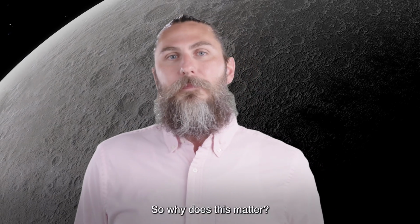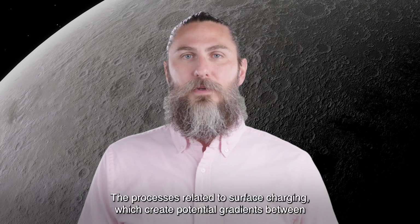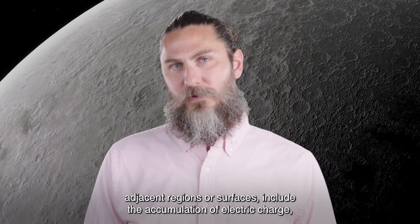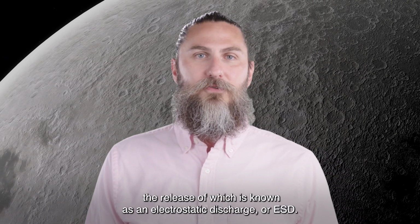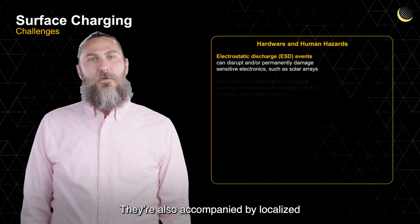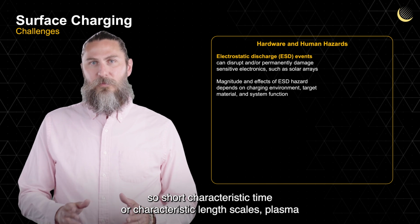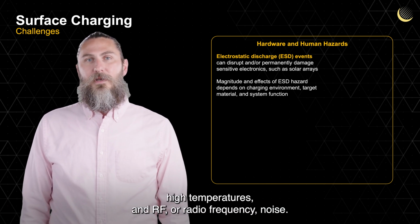So why does this matter? The processes related to surface charging, which create potential gradients between adjacent regions or surfaces, include the accumulation of electric charge, the release of which is known as an electrostatic discharge, or ESD. ESD represents the release of this stored charge. It is also accompanied by localized, so short characteristic time or characteristic length scales, plasma, high temperatures, and RF or radio frequency noise.